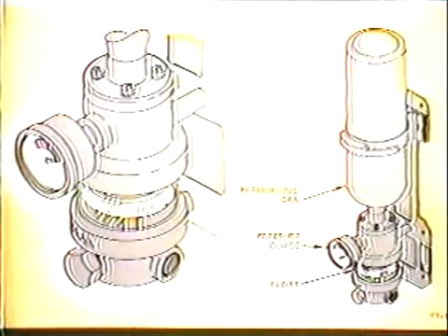The rain repellent pressure gauge has a red and green arc. There is also a refill sight gauge below the pressure gauge. If the pressure gauge indicates in the red, or the refill float is in view, the system requires servicing.